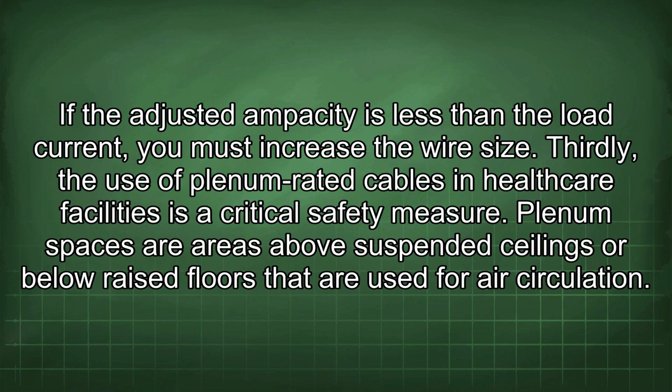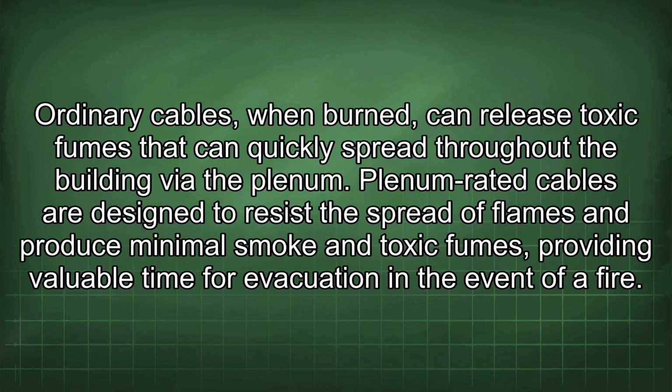Thirdly, the use of plenum-rated cables in healthcare facilities is a critical safety measure. Plenum spaces are areas above suspended ceilings or below raised floors that are used for air circulation. Ordinary cables, when burned, can release toxic fumes that can quickly spread throughout the building via the plenum. Plenum-rated cables are designed to resist the spread of flames and produce minimal smoke and toxic fumes, providing valuable time for evacuation in the event of a fire.